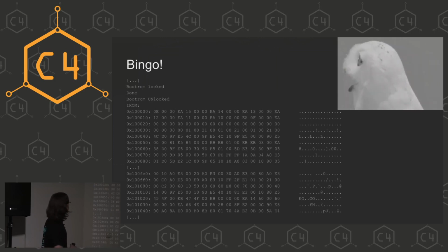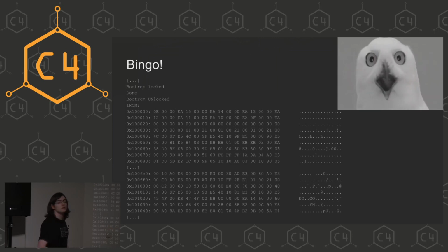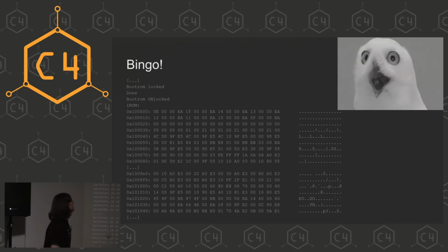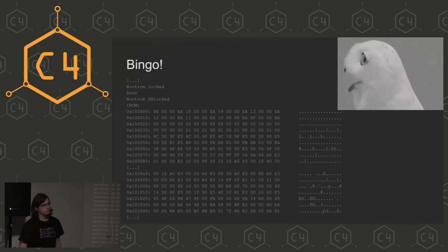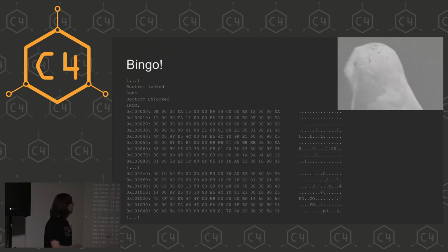Because we can see this is again the hex dump, this is what we saw earlier, same stuff. And then here at 0x1000, earlier we saw this jump 0, and suddenly we get stuff back. And it looks like the other code. So we got the boot ROM. This was running in a screen. I just dumped everything into a file, wrote a script which parses my hex dump code, wrote this into binary, and opened up a beer.